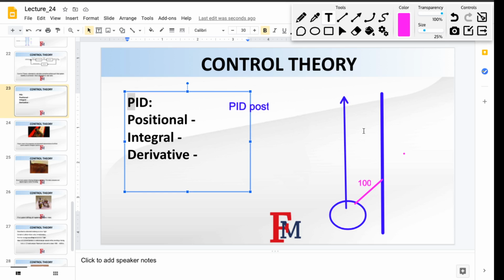So you always want the distance between the robot and the wall to be constant, and the sensor should always sense 100. It doesn't really matter what it translates to, but I remember 100 being one of the best values. So let's say that's your decision. The idea is that every single iteration of a while loop, or every discrete moment of time, for example, you decide to sense the wall every other second. A second later from that moment, you will be located somewhere here.